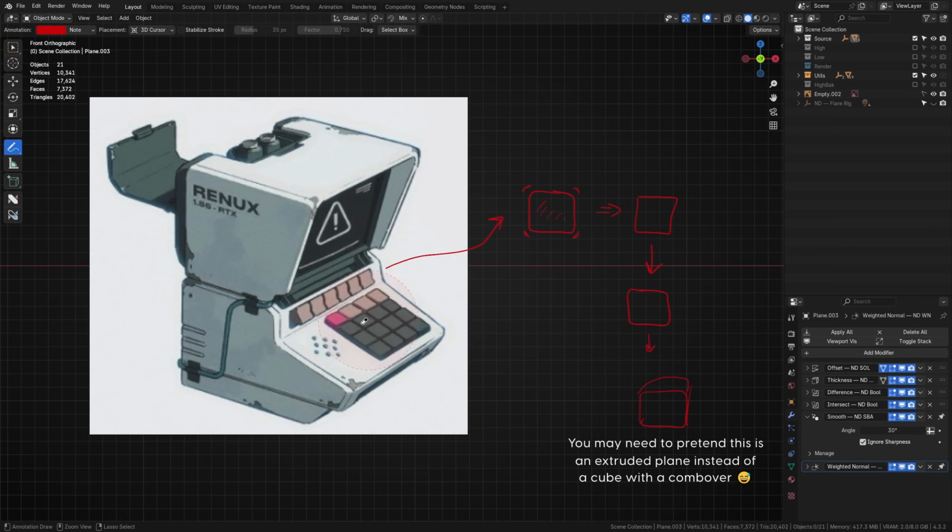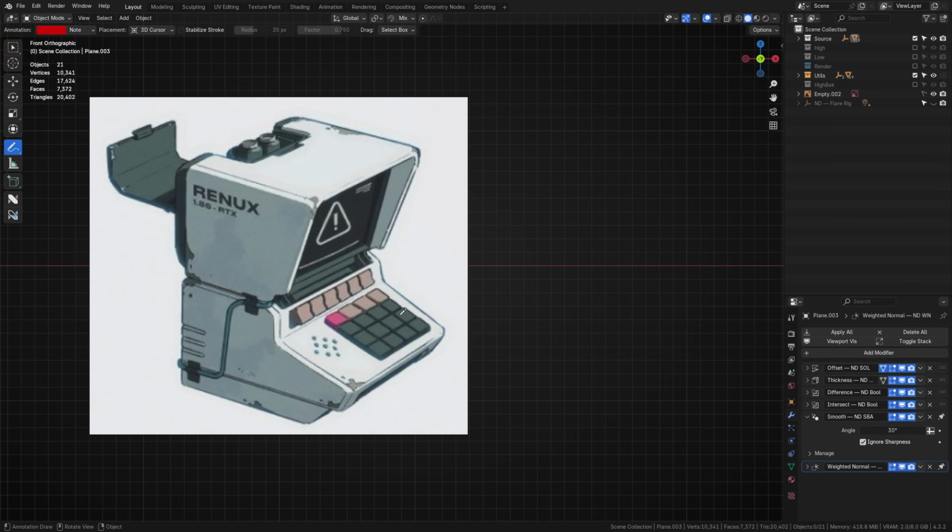The image is a little grainy, but because I can see what appears to be a chamfer around the top perimeter of the button, I'd like to add that in as well. We know that we can add this effect, but it will be applied to both the top and bottom of the object, which is fine with me as the bottoms of these buttons aren't visible anyway. Later, once we've finished modeling and are ready to clean up these buttons, say for UV unwrapping and preparation as a game asset, we can apply all the modifiers and then delete the unnecessary geometry. To finish this detail, I'd then array the buttons along one axis, creating a single row. Then I'd array it again, creating multiple rows. Let's look at this on the model itself.